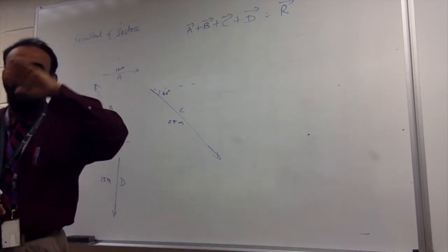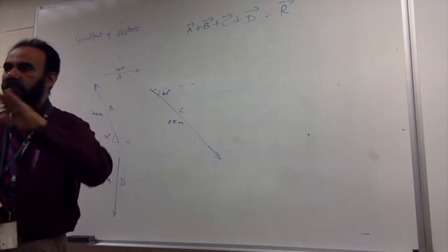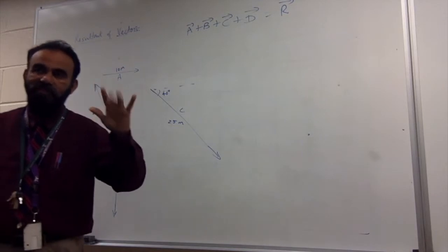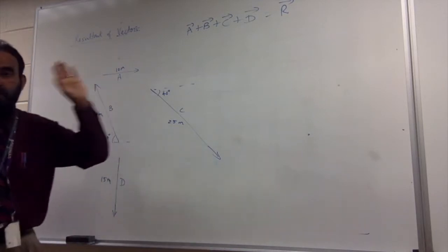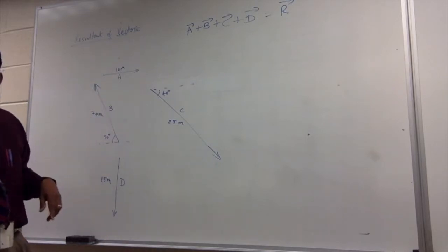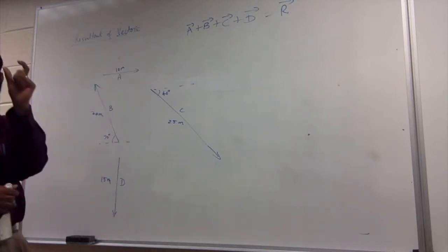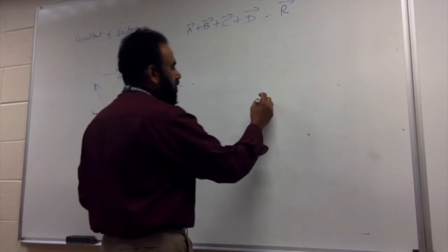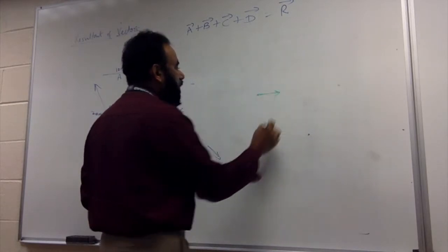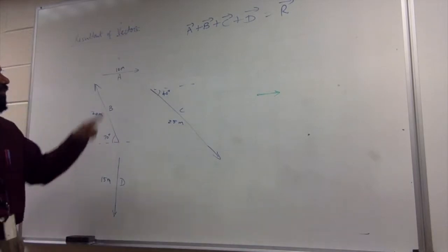So what's the ratio there? 1 to 5. 1 to 5, but remember, I'm changing units as well, okay? Just keep in mind. So here is meters, but I'm going to draw centimeters. So instead of drawing this, I will draw 2 centimeter line. So starting from somewhere, I'm drawing a 2 centimeter line. That is 2 centimeters across.